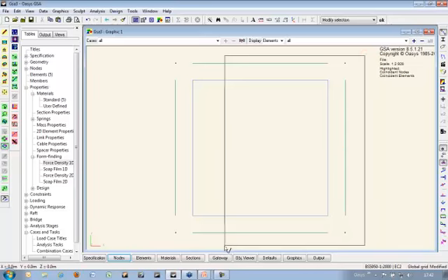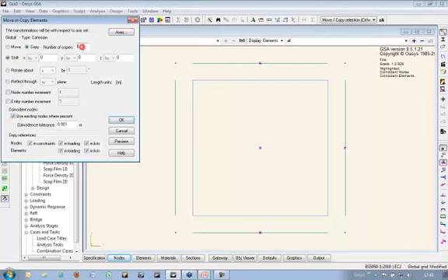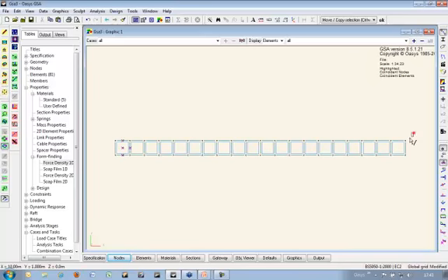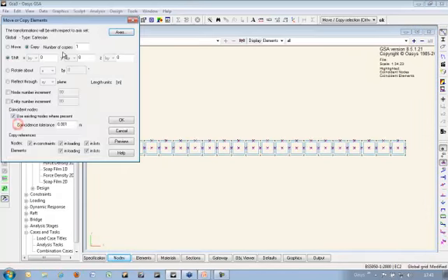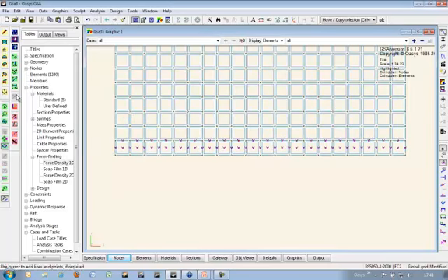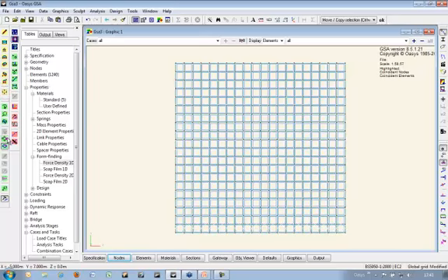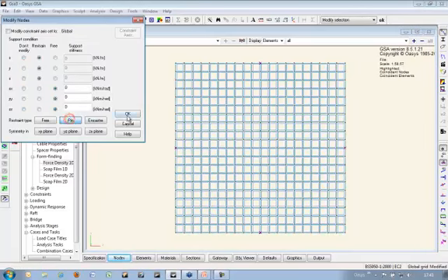So if I just take this little arrangement, I'm going to copy this. This is a half meter, so I'm going to copy it to create about 10 meters square, and likewise select those, copy that, to get my total grid, and I'm going to pin the midpoints. The tooltip is quite useful because it shows up the coordinates, and then modify it and just pin those